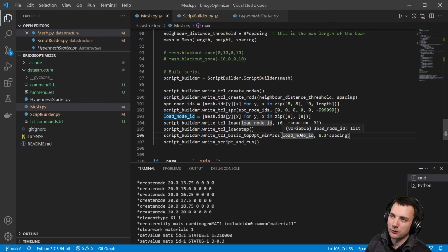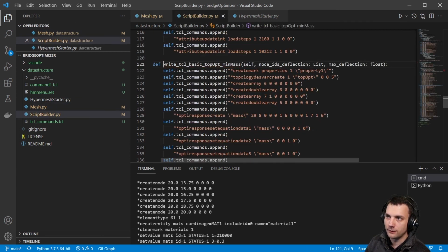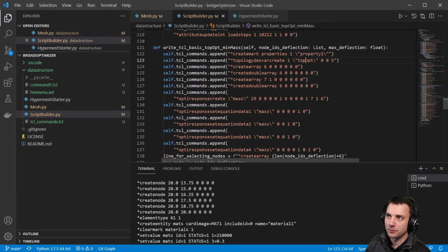On those nodes, the displacement constraint is active, and this is the amount of displacement which is allowed as max. It's taking the sum of the displacement, so all 3 components, so the total displacement. And this is just using the property which you have assigned also here. Has to be done better in the future, not hard-coded names like that.